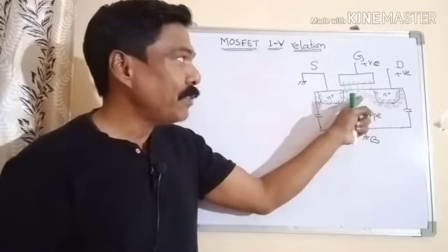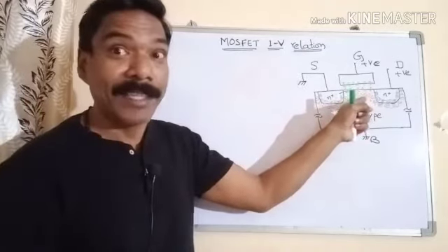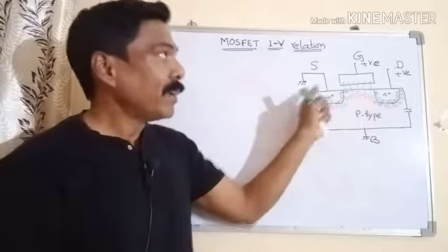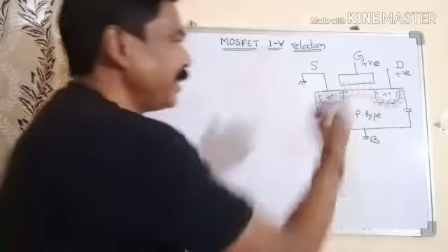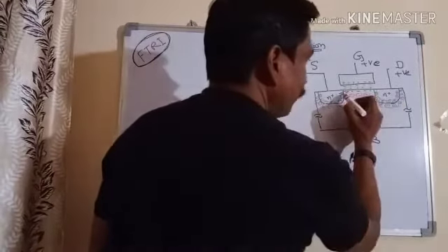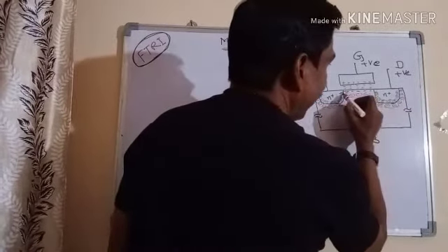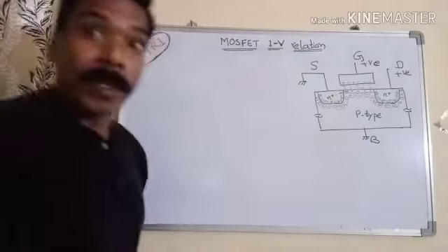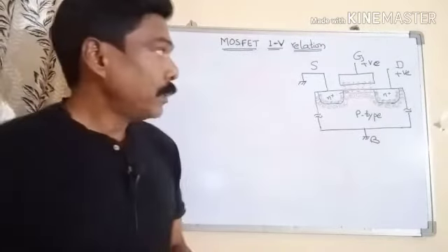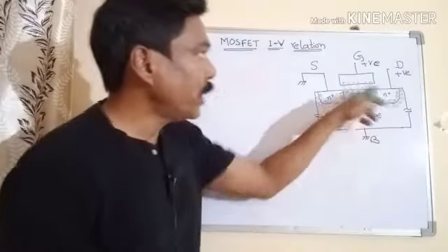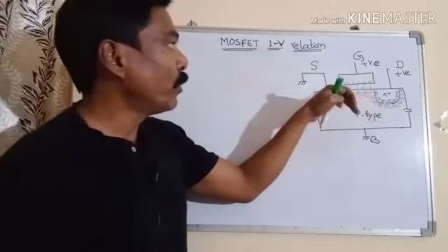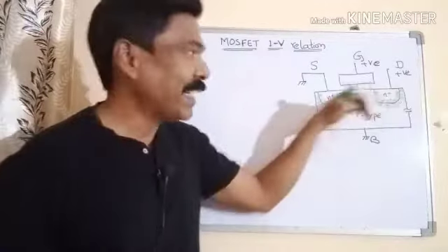So the negative charge which is balancing the positive charge in the dielectric will now be collected from the source. They are the mobile electron charges, electron carriers. So this is called a channel here. These mobile carriers are acting as the channel, which is used for conduction. Through that channel there will be a current flowing from source to drain. So it is acting as a channel actually.